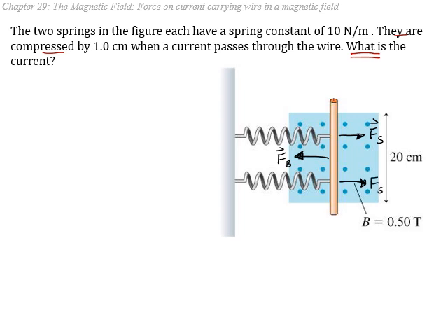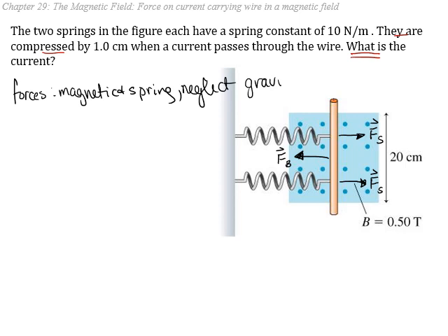Another spring force. Okay, so now we have a free body diagram where the forces we have in our diagram are magnetic and spring force. We're going to neglect gravity. Let's assume that our rod is light enough that the gravitational force is small compared to our spring force and our magnetic force, and that our bar doesn't actually droop very much.